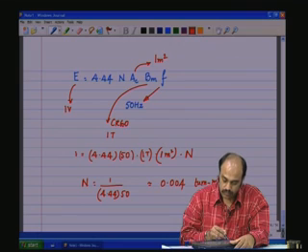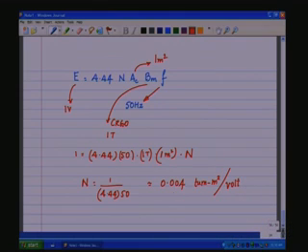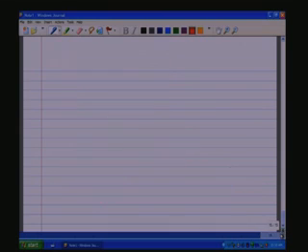This is for 1 volt, so many turns for 1 volt, and the area comes in, so that is the meter square per volt. This would be an approximate thumb rule which will give you at least a figure of what will be the order of magnitude of the turns that you would be applying.